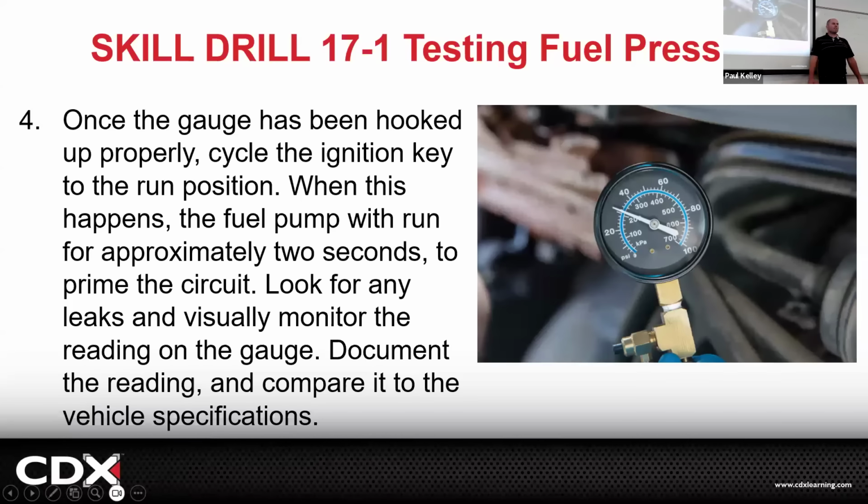What if the spec was 50? Is this good or bad? Spec is 50. It's only got 30. It's gas savings. Well, and power loss as well. So if the car doesn't start, what do you expect your fuel pressure to be if it won't run at all? 0. Pretty much 0. I agree. So if you're doing a no start and you got 30 PSI, I'd be like, that's kind of low, but I don't think that's causing the no start.